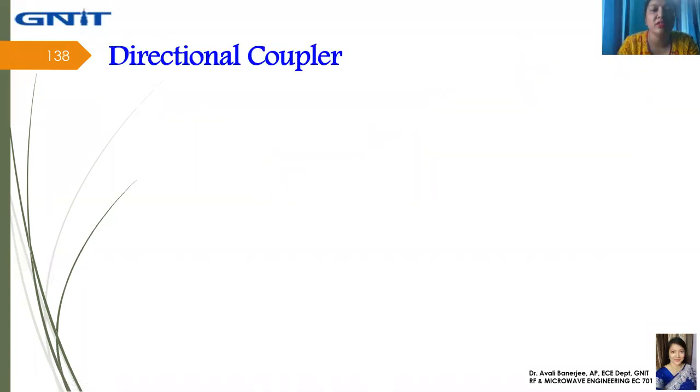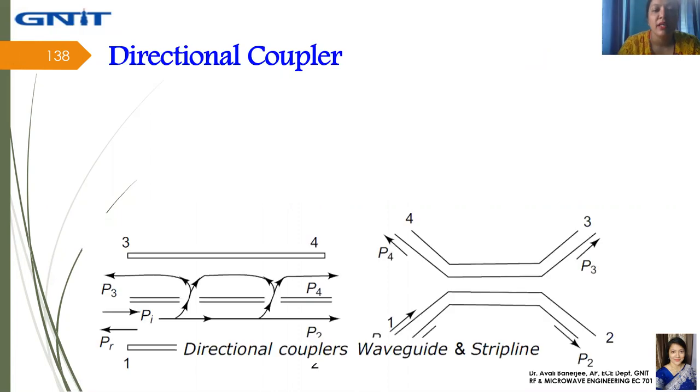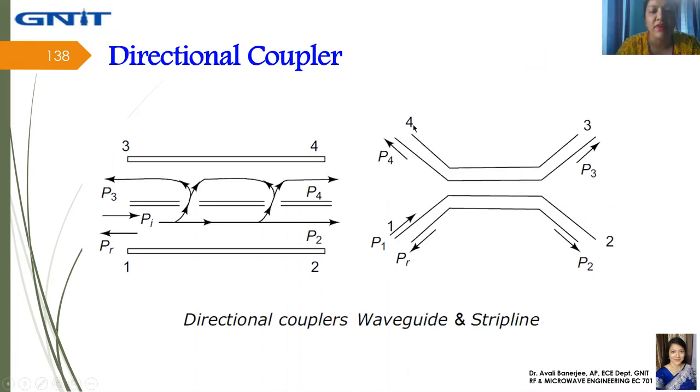Now moving to the next component, that is directional coupler. A directional coupler is a 4-port passive device commonly used for coupling a known fraction of the microwave power to a port, that is the coupled port, in the auxiliary line flowing from the input port to the output port in the main line. The remaining port is an ideally isolated port and match terminated.